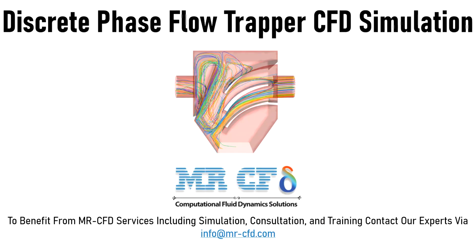In this project, we will simulate and analyze the flow of a particle trapping mechanism called the discrete phase trapper. In order to simulate the particles, the discrete phase model is activated, and Saffman lift force and pressure gradient forces are also applied to particles. Also, since the trapping mechanism mainly works with gravity, gravity has been taken into account.